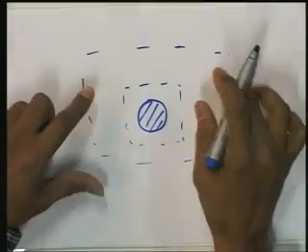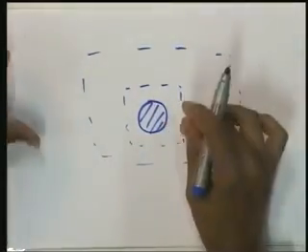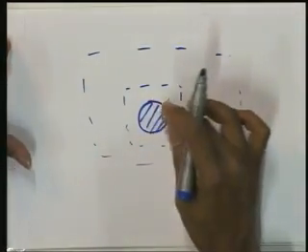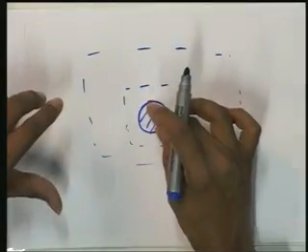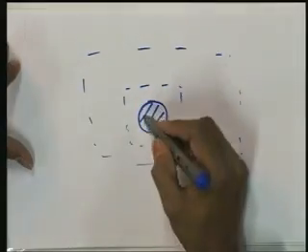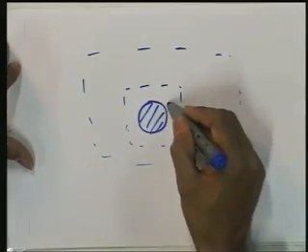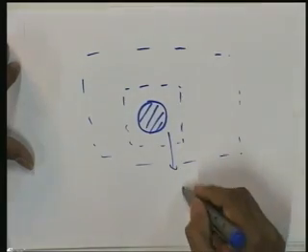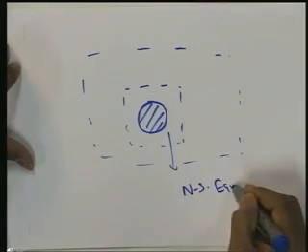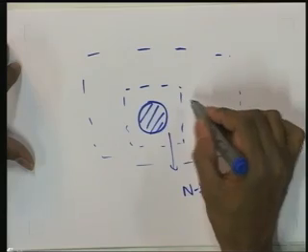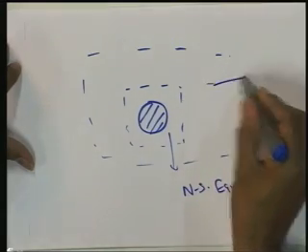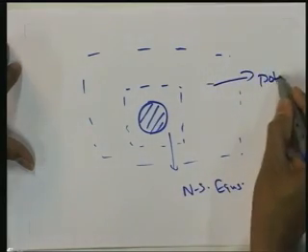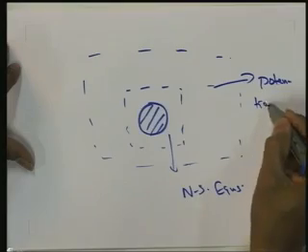Near the solid boundary, viscous effects will definitely be there and boundary layer formation takes place. So, in this region we can directly solve the Navier-Stokes equations, and further away from the boundary we can consider potential flow as an approximation.